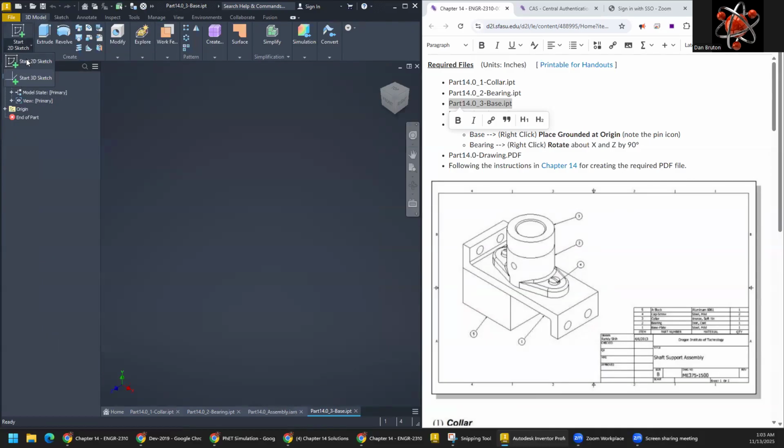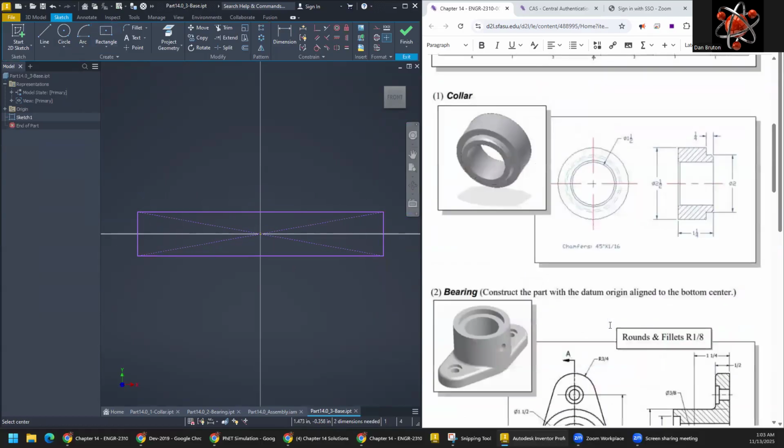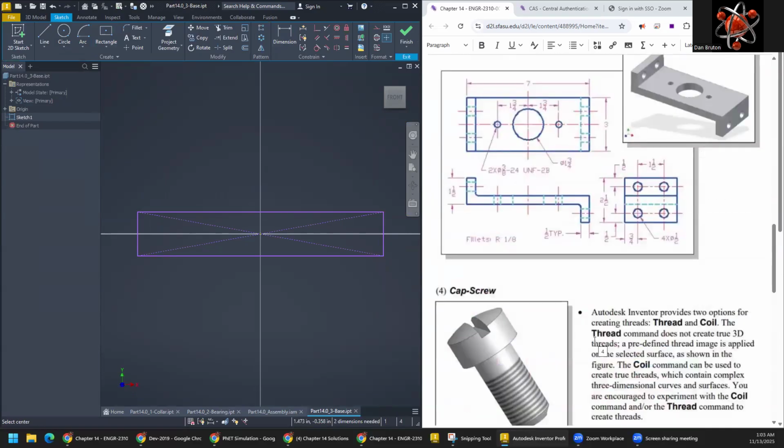And then begin our two-dimensional sketch. Probably on the side is good. And then just a bunch of rectangles, right? So maybe the center rectangle would be the thing to choose here. A slab, like so. And then we look at the dimensions of that slab, and we see that the whole width of this needs to be 7 inches.